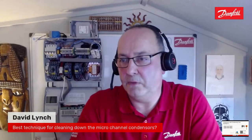Now, the microchannel condensers, basically the dirt, let's call it dirt, the fluff, basically sticks to the outside of the condenser like a mat. So the best way to clean a microchannel is with a stiff brush, and I'm talking, not a wire brush, please, just a stiff nylon brush, and clean the dirt off. That is the best way to clean a microchannel.